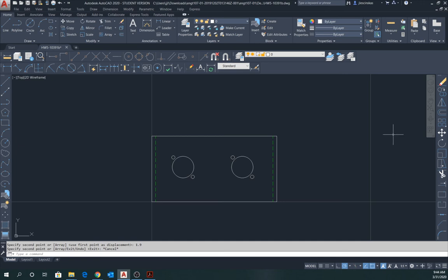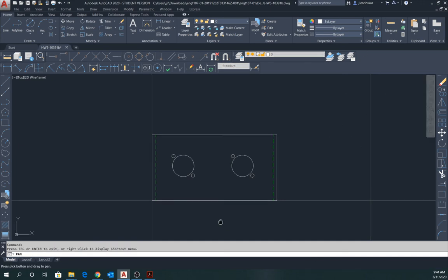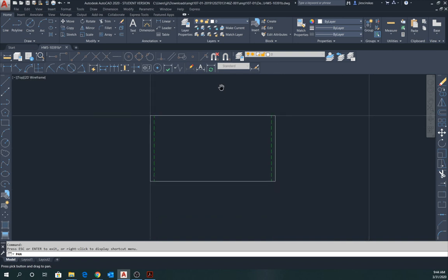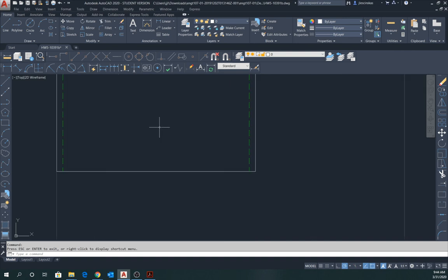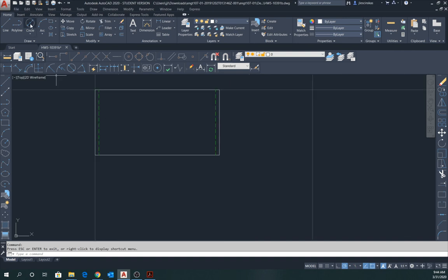So we go back to AutoCAD. Come over here, pan all the way down to this drawing. Choose our circle, snap from, and then choose this point. And I'm going to let you guys in on a secret. I don't have great memory. I'm able to cheat. Unlike what you guys have, I have 4 monitors in front of me and 3 computers.